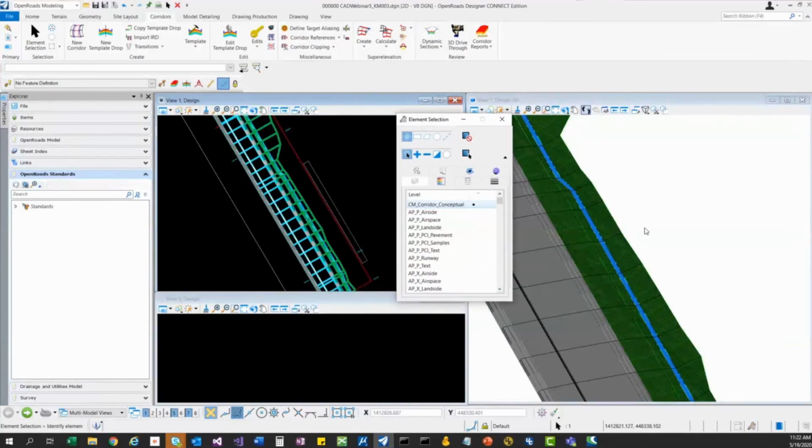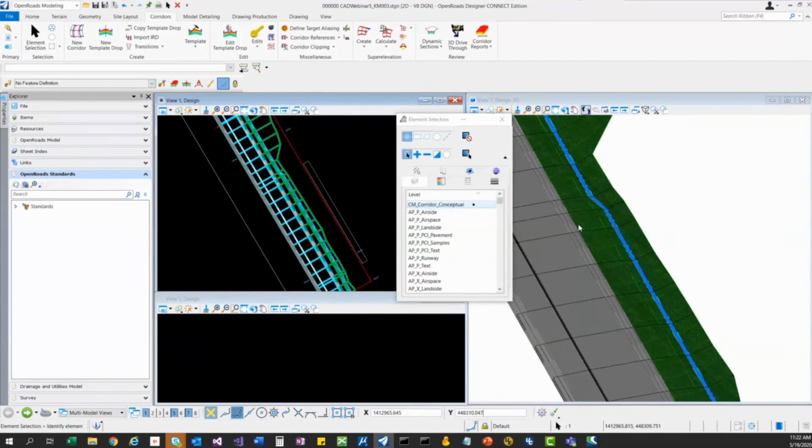All right, so since our point names are set up pretty well, when you do stuff like that, you'll see that when it transitions between different slopes or different end conditions, the points and components connect nicely. And that's because we do have a standard naming and template set up to alleviate that issue. But that's not always going to solve the problem, right?